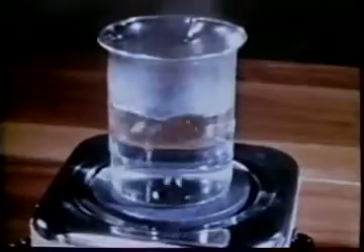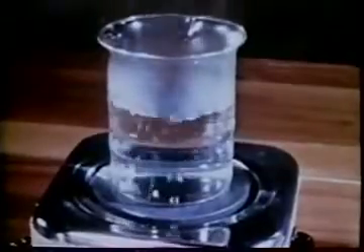We apparently see many being generated in boiling water, for example. These, and practically all of the bubbles you will ever see, are not new. They are pinched-off enlargements of other bubbles, usually of vapor pockets in cracks where liquid has never completely penetrated.